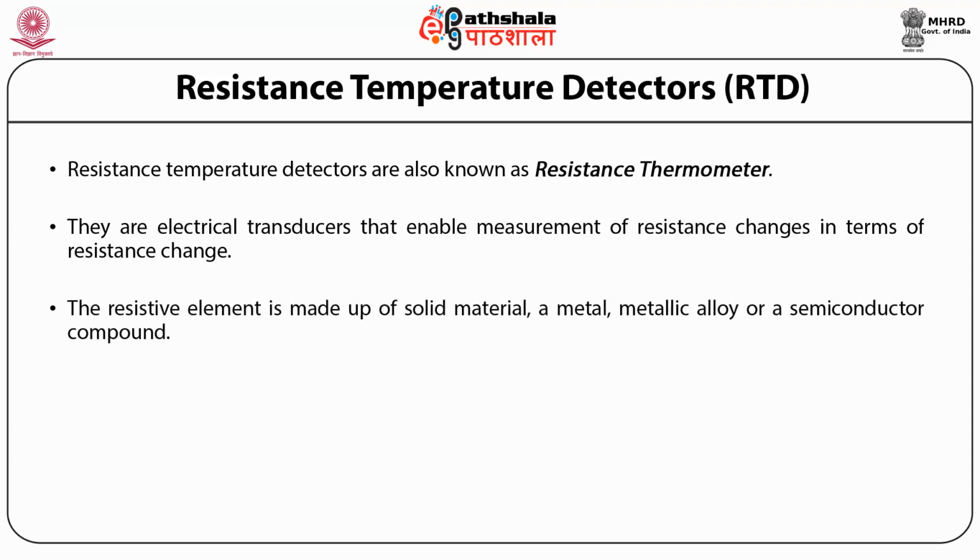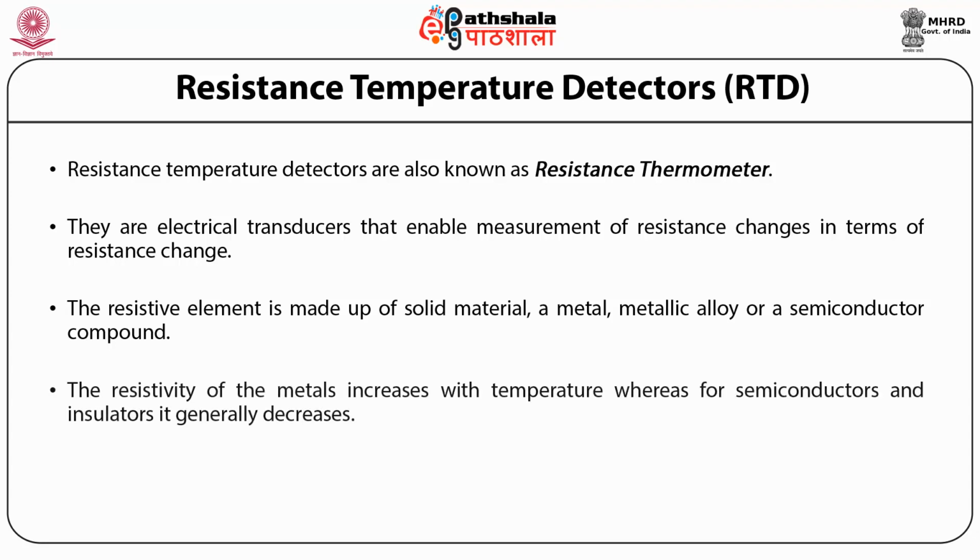The resistive element is made up of a solid material, a metal, a metallic alloy, or a semiconductor compound. The resistivity of metals increases with temperature, whereas for semiconductors and insulators it generally decreases.